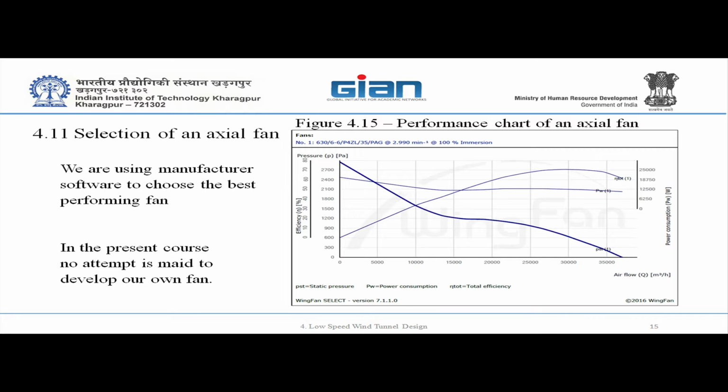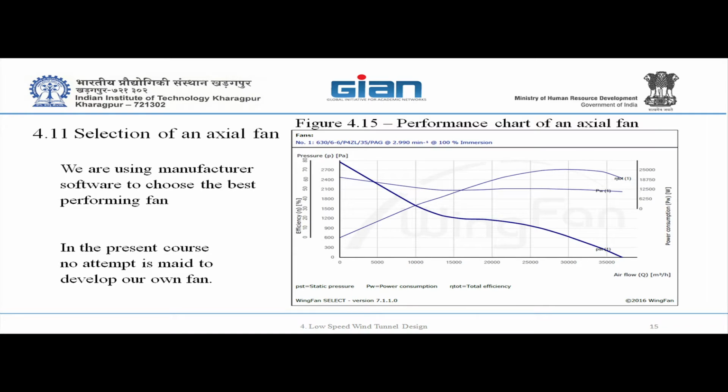Is it advisable? Is it a good idea to have a wide angle diffuser in front of the fan? Yeah, you want it. Why do you think so? Because stream-wise you have the increasing pressure in front of the fan, just in front. The main energy you have to contribute is in the test section. You accelerate the flow from 0 to test section speed. This is the main energy. Later on, losses are only due to friction, nothing to do with pressure.